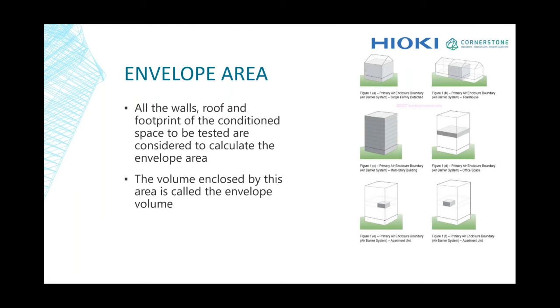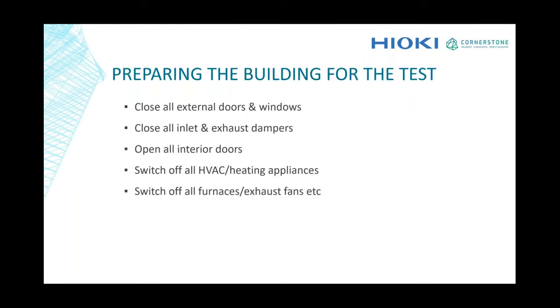Okay. So preparing the building for testing. For preparing the building, we need to firstly close all the external windows and doors. That is done in order to ensure that the building is at its maximum airtight situation while testing.